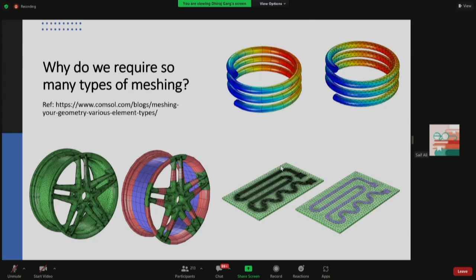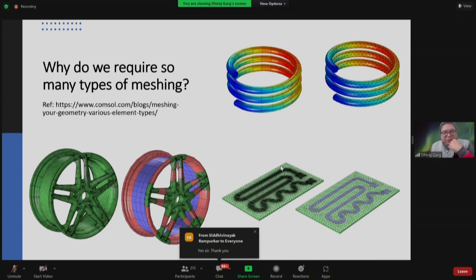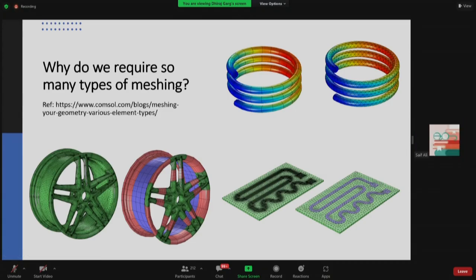Sir, if you wanted to know how much time the liquid would spend inside this, could you do that? So you want to know the time, basically it's the residence time. That is the total volume of this structure divided by the average velocity. That will give you the average residence time. One thing is, if you already know it, then it's fine. If you want to calculate it, then you can do the experiment.